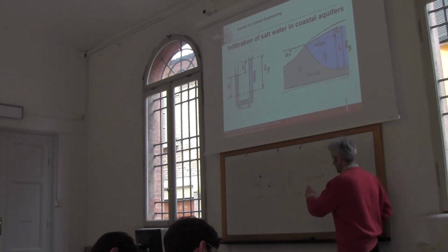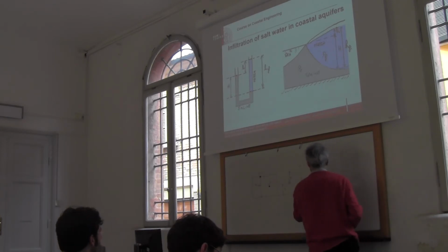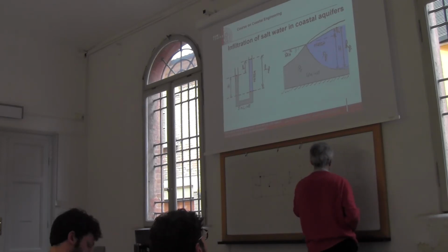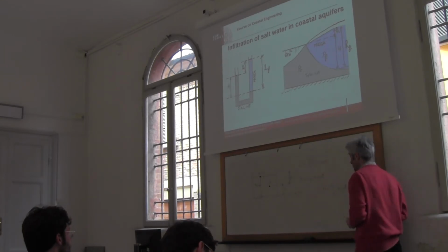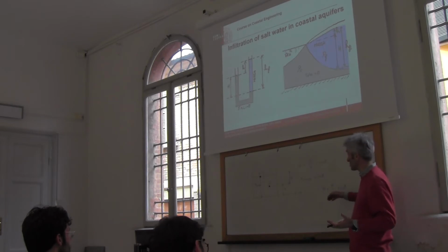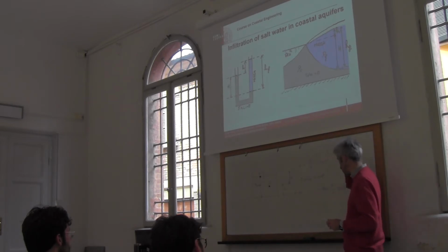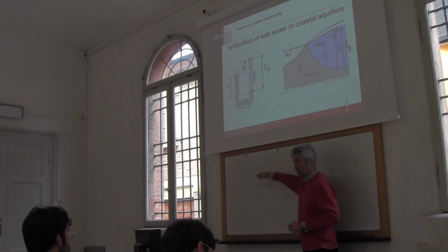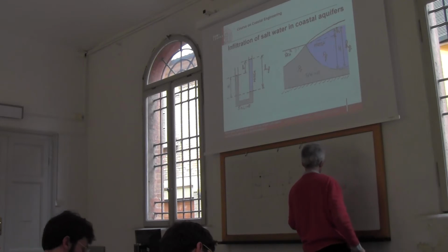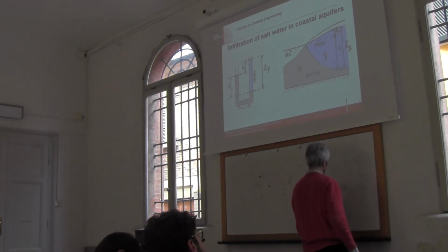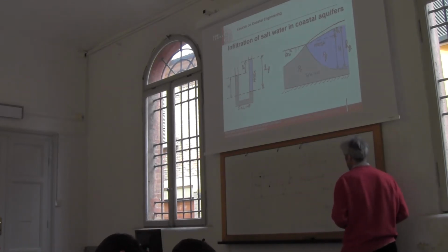So if I want to make reference to H, I should write minus H plus P divided by gamma is equal to a constant, and the constant is different, it changes, because now I'm making reference to the surface of water. I would say that 0 plus 0 is equal to my constant, and therefore the constant is 0.